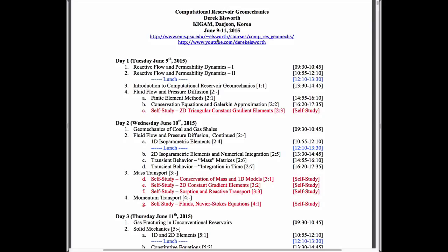And then what we did with that was we inserted Darcy's law, if you remember. So Darcy's law is actually the way of being able to include both the inertial and the frictional drag effects that you'd see in Navier-Stokes equations. And so when we deal with porous media flows, the way that we deal with it is a different way than dealing with it in this way. It's perfectly adequate. But the Navier-Stokes equations are actually full momentum balance equations.